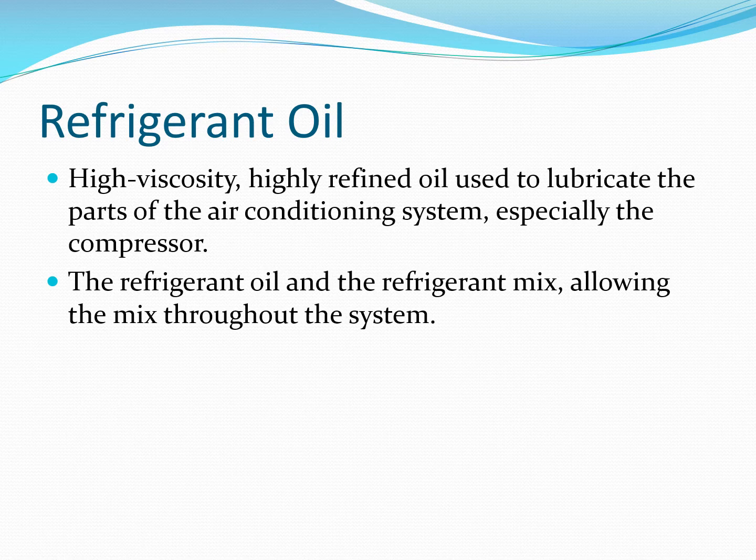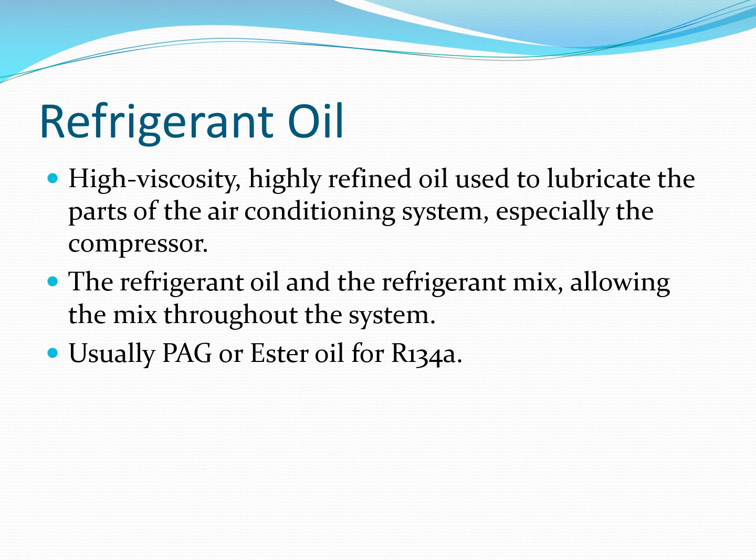oil the system is using. Make sure that if you have to add oil to a system or if you have to replace a component, you are using the correct oil for that given system. A 134A system is usually going to use PAG or ester oil. Again, you don't want to mix these two, so you need to make sure you're putting in what the manufacturer recommends for that given vehicle.